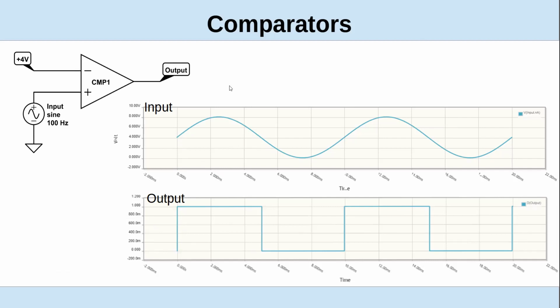So would they use something similar to that when someone has grid tied solar to make sure that they're in phase with the grid system they're tied to? Possibly. Anytime you need to compare a signal to a fixed voltage on whether it's above or below, that's the information it tells you, that you've crossed that threshold.